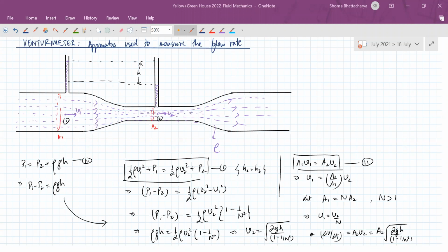No, Diti, the pressure is greater at the point 1 because the speed is less. Bernoulli's equation clearly says where the kinetic head is less, the pressure has to compensate by being larger. You can understand volume elements of liquid are accelerating as they go from 1 to 2, so the pressure from this side has to be more. It's counterintuitive. One thinks that if it is narrow, the pressure should be greater, but it's actually not that way. And that is what Bernoulli's equation tells us.